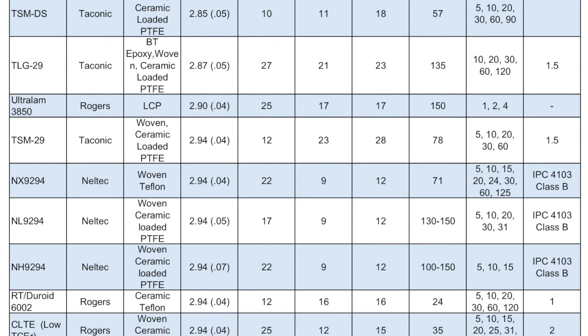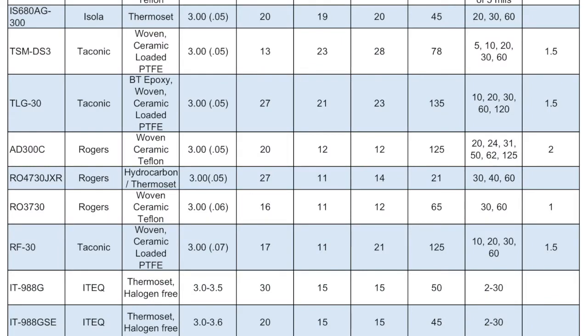Okay. So when you get a new design for an RF microwave type product, you must spend a lot of time with the customer early on material selection and trying to match to the application. Yeah, there's a lot of going back and forth because most often people select very low loss materials, or they know that their circuitry will generally function well with the highest performing materials available. Then you have to go through the set of trade-offs that presents.